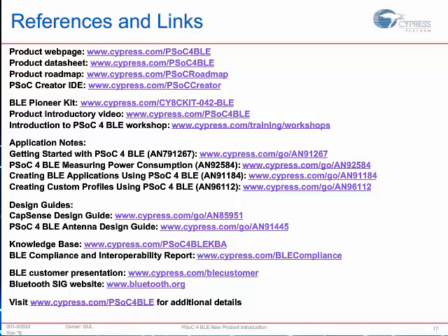Does the BLE stack utilize onboard flash? Typically that's about 128 or 256, depending on the chip. Yes. Another good question. So as you recall, this chip is available in two memory footprints, a 256K version and a 128K version. The BLE stack consumes a portion of this flash. Depending on how you configure your BLE stack, which is specific to your profiles, it can consume anywhere between 70 to 80 kilobytes. So on a 128K chip, you're still left with about 50 or 60 KB of flash after the BLE stack has been implemented. But on the 256K, you have another time and a half space of flash available, which is excellent because it can be used to create some really intensive applications, or if you can create your entire stack plus application inside the 128K, you have another 128K remaining to perform over-the-air firmware upgrade.